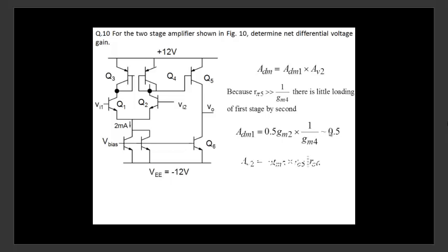Okay, the next stage, the gain of the next stage. When I look at the next stage here, it goes to the base of this Q5, and it's a common emitter amplifier. We are asking for voltage at this particular node here. Note that there's nothing applied to Q6 here, no voltage is applied. So Q6 is nothing but bias under small signal condition. This would be small signal ground. So when I look down, this is ground, and I see into the collector of Q6, and what I see is ro6. So as I said, it's a common emitter amplifier.